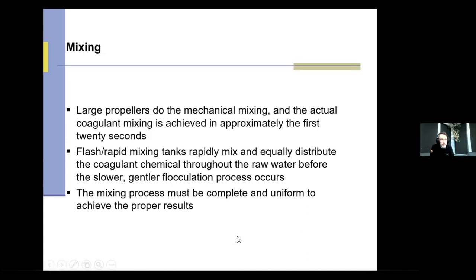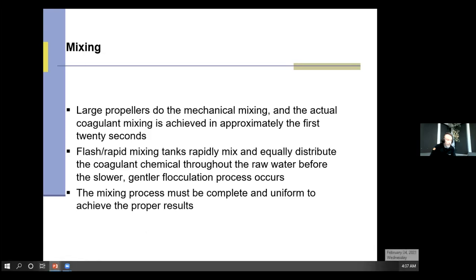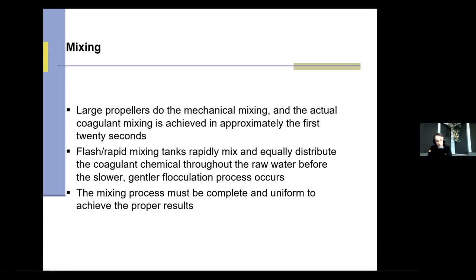One of the big things, the mixing process must be uniform, and that's the biggest thing. We want to make sure all that water in there is mixed properly, and it's mixed in a way that it's always consistent. Because if I'm only mixing some of my water and maybe we're overdosing some of it and underdosing other parts of it, that's not going to make for a good treatment process, and you're going to run into some trouble there.